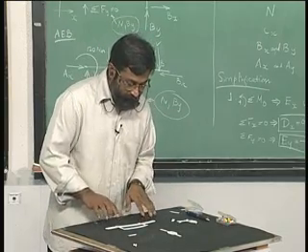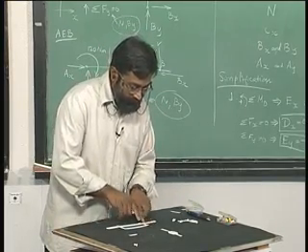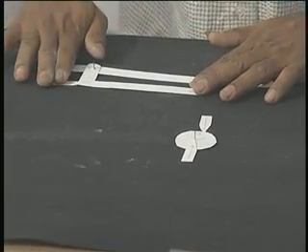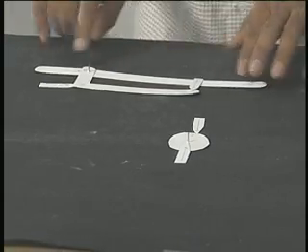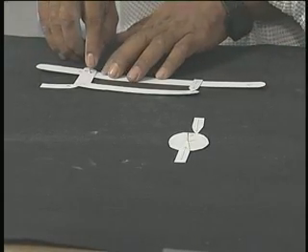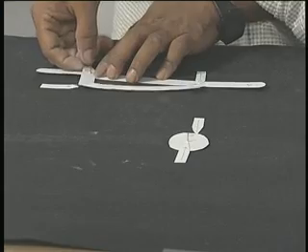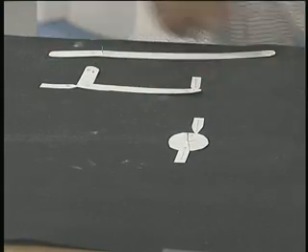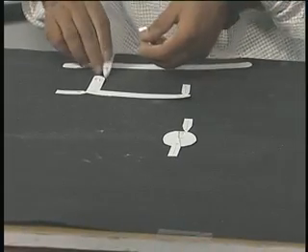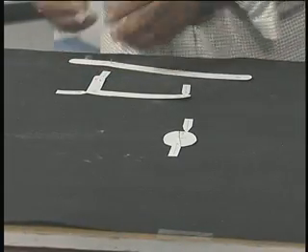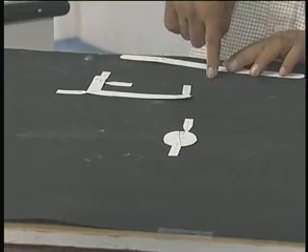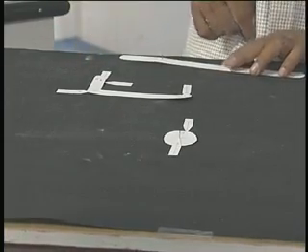Now if you look at it, if I have a force over here, let me retain that force, there is another force on this. If I have to remove AEB now, I have to remove the restraint here. When I remove the restraint here, I need to add the two restraints related to that, and this is the free body diagram of BCD.